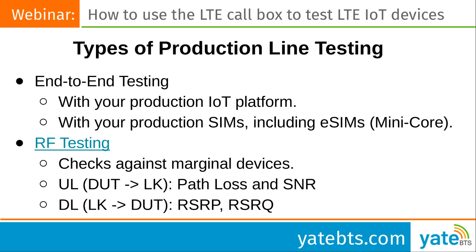So what are the types of testing that you're going to do here? The testing really falls into two parts. There's end-to-end testing and there's RF testing. Because the LabKit gives you a true full-blown LTE network, you can do the end-to-end testing with your standard production IoT platform and with your standard production SIMs. And if you have a MiniCore, this would include even doing testing with eSIMs.